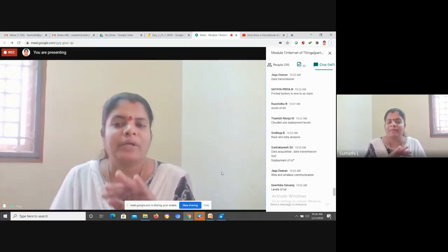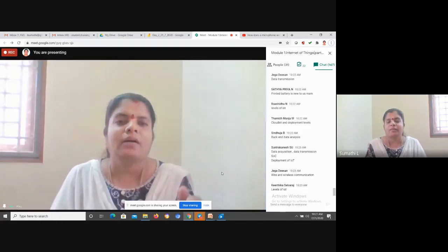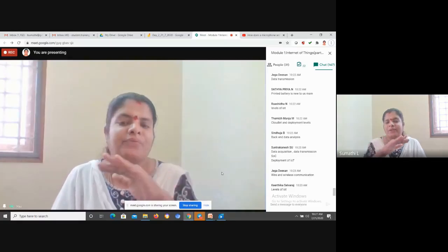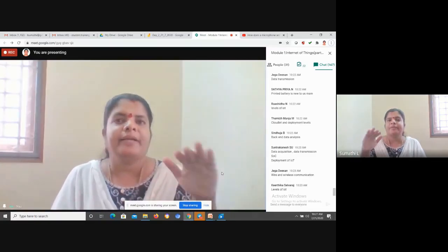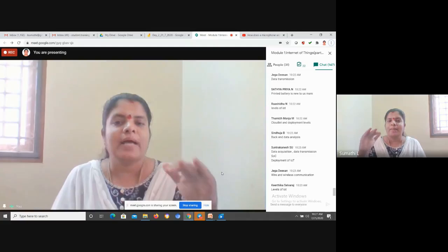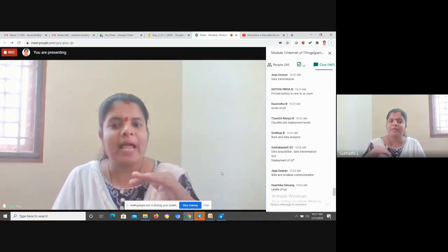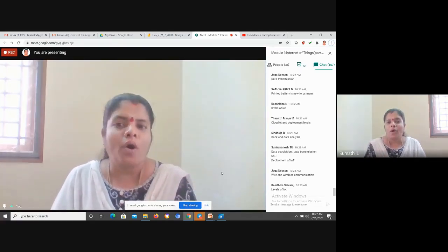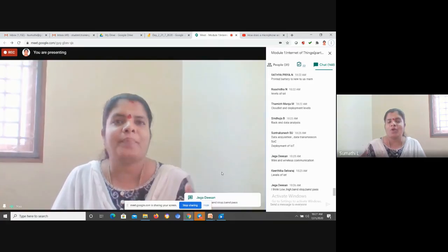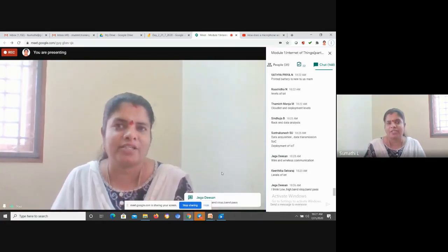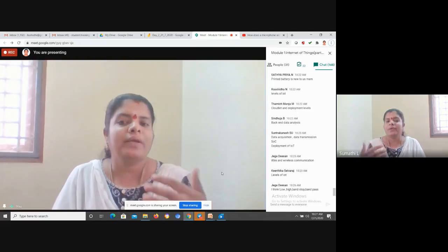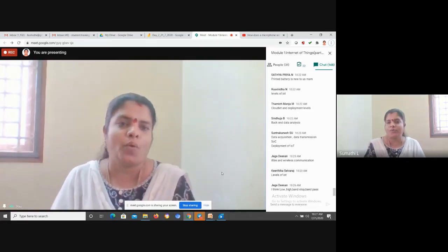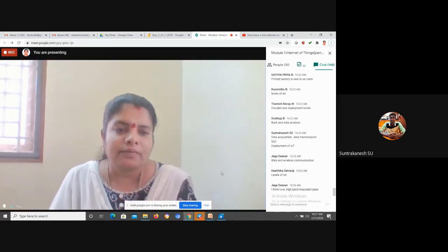As of now, I will give you a high level abstraction. The example we picked and showed is the low pass filter. That is, I set a frequency range, right? If the signal frequency is below that threshold I will allow it to pass, otherwise I will cut it off. Why we picked the low pass filter: normally the signals generated by your sensors are low frequency signals, right? So we use a low pass filter over that. Okay, ma'am.